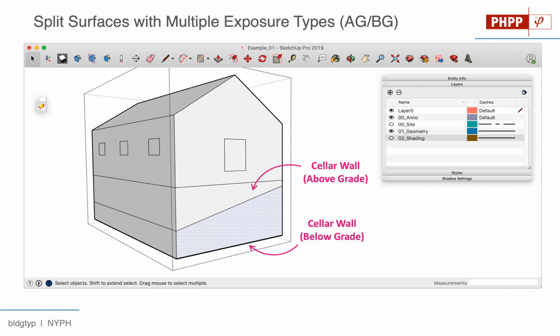And the long and short of it is that it's almost impossible to use the native or raw architecture 3D model. You're really building out a purpose-built building information or building energy model, which is going to be built and adapted and tweaked to exactly what the PHPP wants and needs. So for the most part, you're going to end up remaking your building model with an eye towards the PHPP.